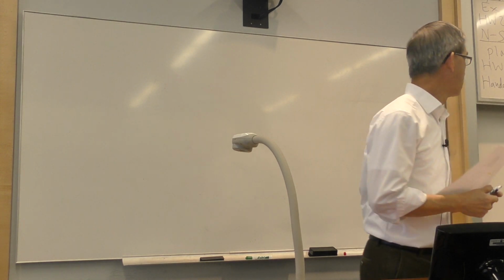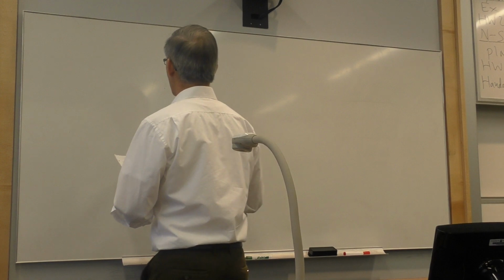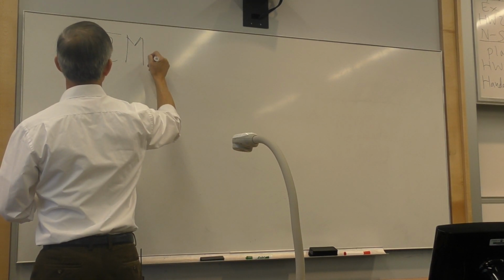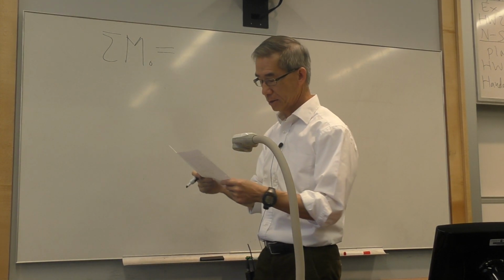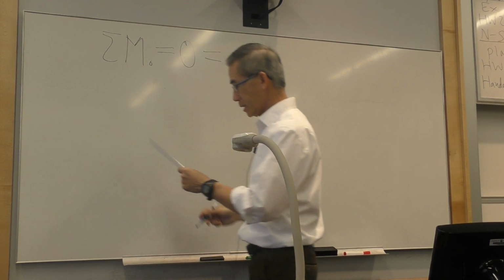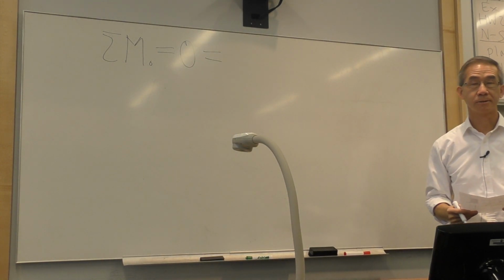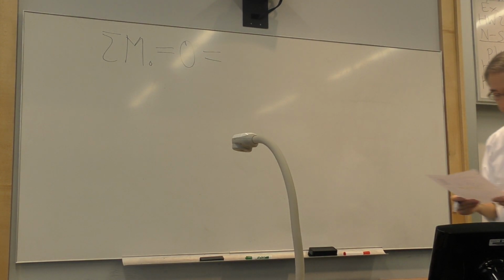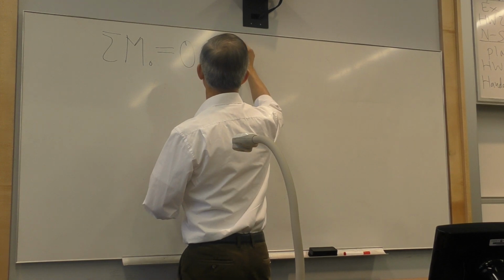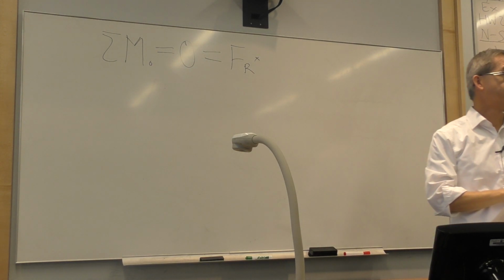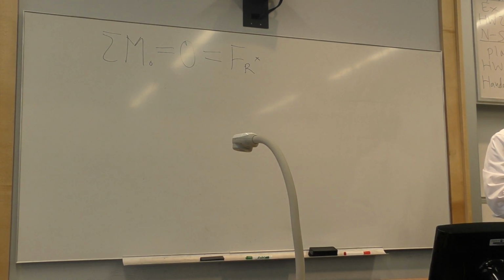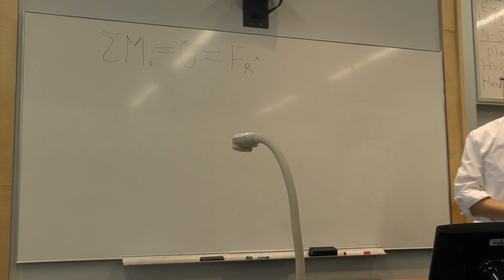So the next big step is now how do I deal with the moment? The moment will be taken about the hinge, which is 0,0. And like your homework before, it has to be 0. Now it consists of, first, that reaction force, which is Fr, times the moment arm. What's the moment arm? From the hinge to the reaction force at the base, what is the length? 0.8?